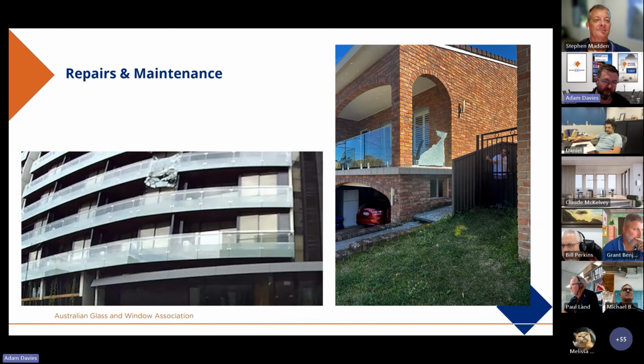one panel, modifying that system substantially to put in glass that is compliant with the current version, considering this is an older barrier system, would I have changed the inherent safety of that system? And the answer may be probably not. But in the case of that same scenario, if you were replacing every panel in that balustrade application, then I would suggest that you probably are making a substantial difference to the inherent safety of the system, and it may be appropriate in that case to then upgrade the supports of the glass to carry the most compliant glass.